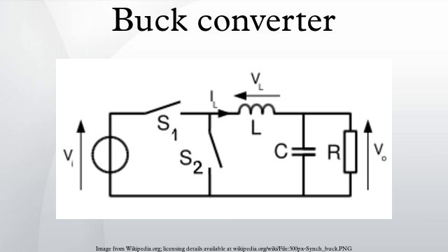Non-ideal circuit. The previous study was conducted with the following assumptions: the output capacitor has enough capacitance to supply power to the load without any noticeable variation in its voltage. The voltage drop across the diode when forward biased is zero, and there are no commutation losses in the switch nor in the diode. These assumptions can be fairly far from reality, and the imperfections of the real components can have a detrimental effect on the operation of the converter.